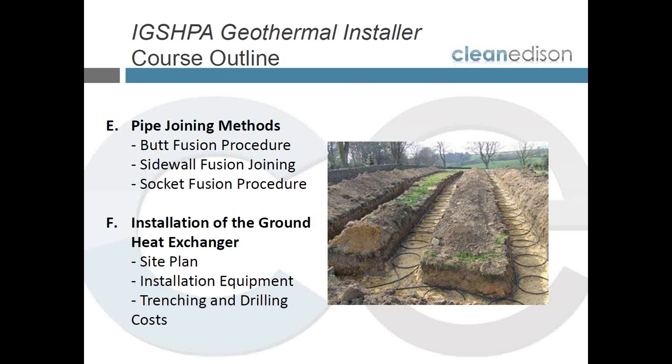So IGSPA emphasizes proper heat fusion procedure, and accredited geothermal installers get hands-on experience in this. Then last, we talk about the installation of the ground heat exchanger with a site plan. We talk about the installation equipment such as well drilling rigs, track excavators, chain trenchers, or horizontal bore machines. And we look at the different trenching and drilling costs.